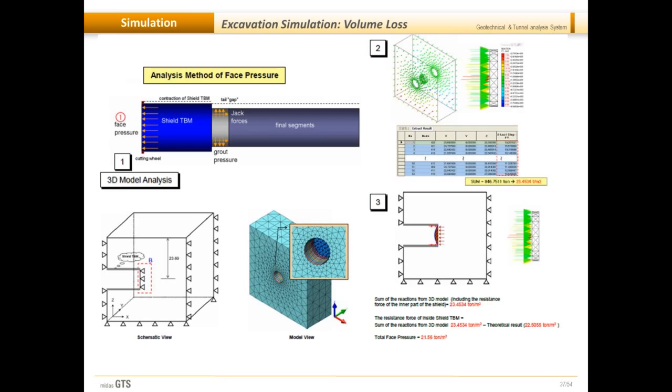So let's say this is the face pressure profile. So instead of this, if I can control my tunnel boring machine and angle and the face alignment, and let's say if I want to increase the efficiency, I want to have a different pressure distribution, I can control that. So here we are not assuming the out of plane behavior. Here we are controlling them by applying the accurate force value and simulating to see how it's going to affect our excavation sequence and thus the ground behavior.